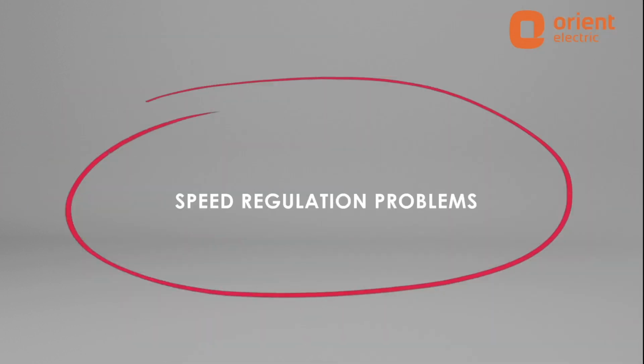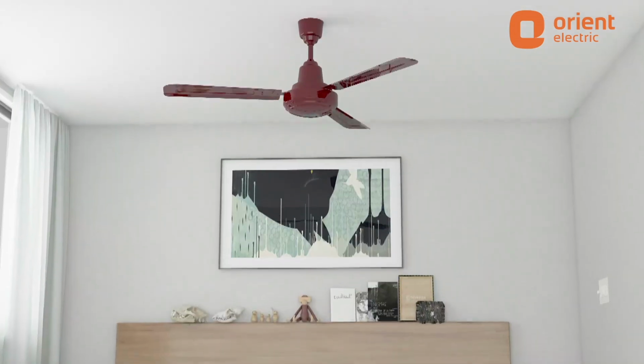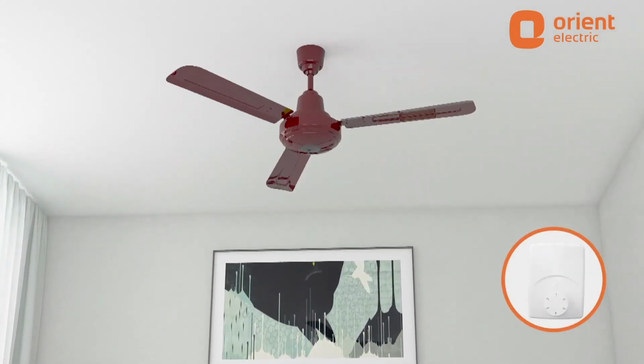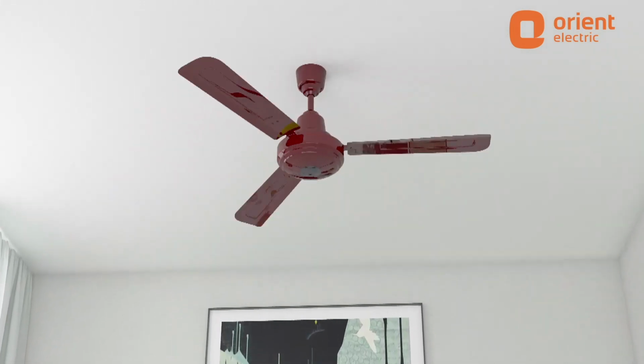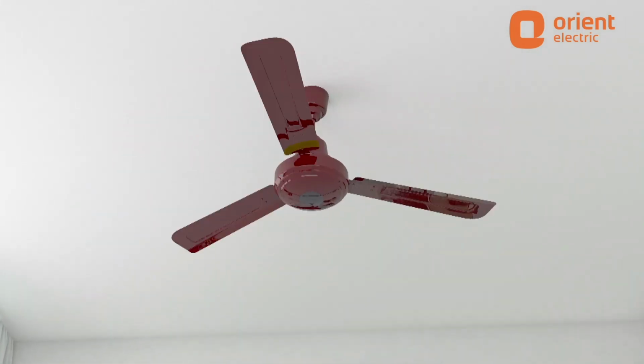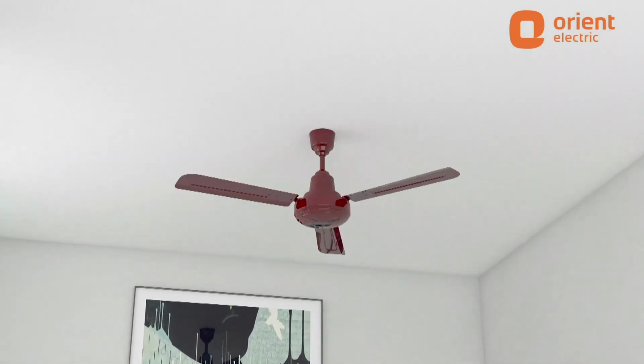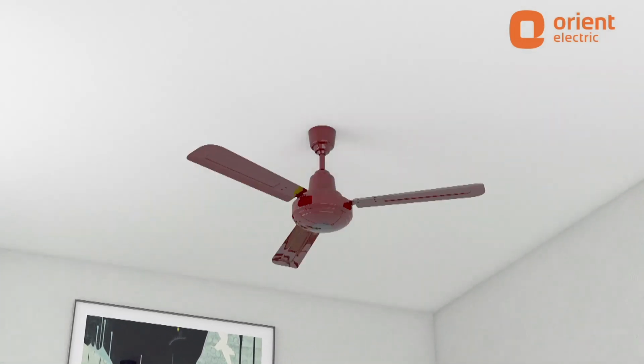Speed regulation problems. The fan speed regulation problem is usually because of a faulty regulator. In this case, carry out the basic checking of regulator like terminal soldering, rotary switch continuity, and advise for change accordingly.